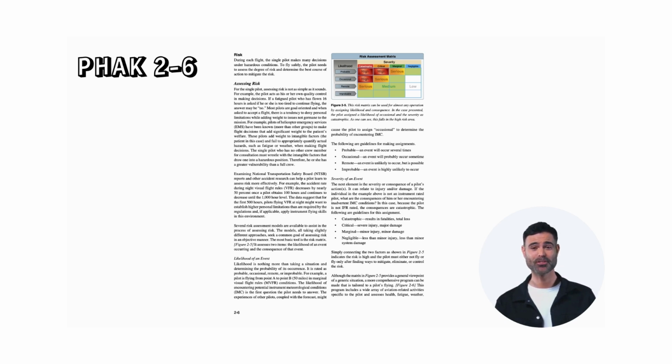The single pilot who has no other crew member for consultation must wrestle with the intangible factors that draw one into a hazardous position. Therefore, he or she has a greater vulnerability than a full crew. Examining National Transportation Safety Board (NTSB) reports and other accident research can help a pilot learn to assess risk more effectively. For example, the accident rate during night visual flight rules (VFR) decreases by nearly 50% once a pilot obtains 100 hours and continues to decrease until the 1,000-hour level.